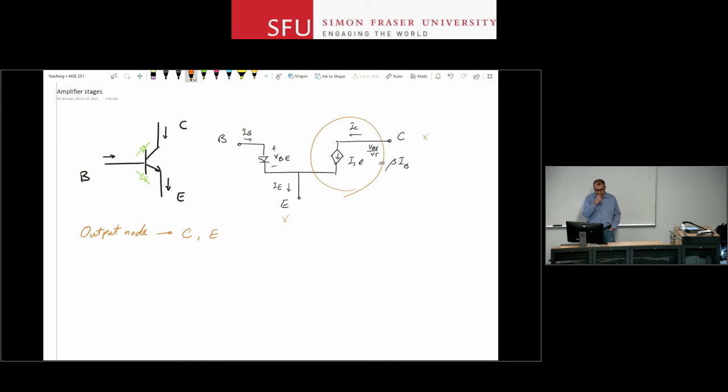The other way to look at it is that, remember, we want to add power to the signal. So let's say if you connect your source to the emitter and put the load at the base side, well, the emitter current is beta plus 1 times larger than the base current. You're actually not going to be able to increase the power at the base side.